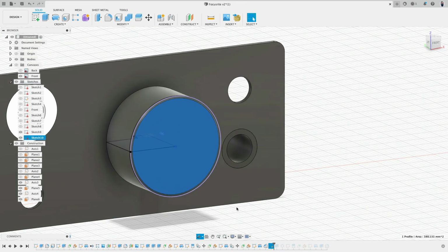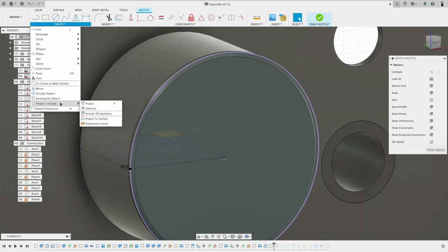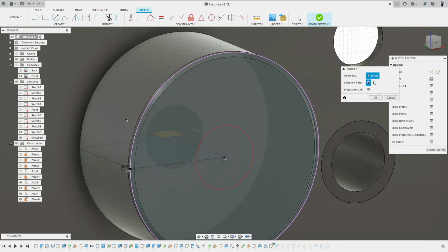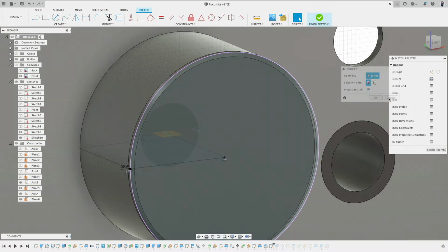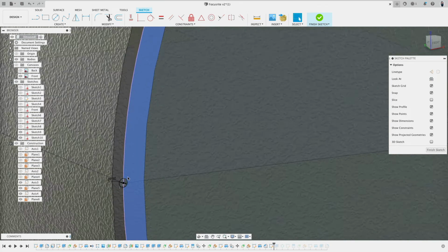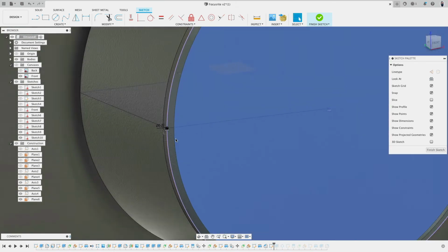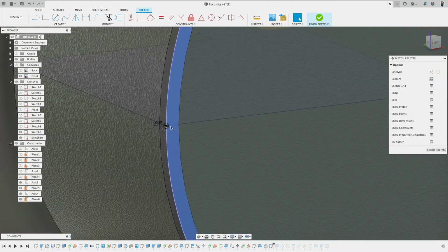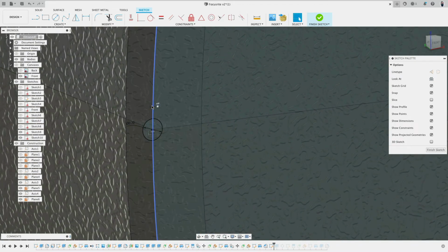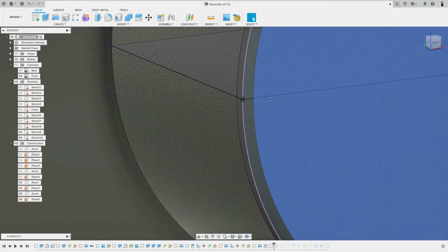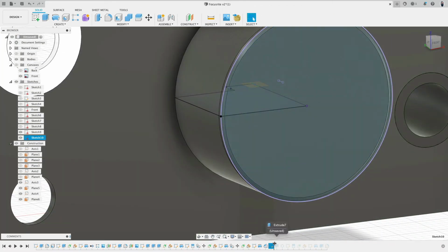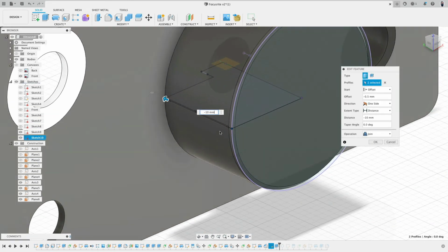Then on this face, we will create a sketch, and I will via project this edge or this face into, actually here, this edge I will project in. That's then the way how I got this. And then I will create there a small, really tiny ring, 0.25 millimeters. There you see, and make this one horizontal constraint to there. And the ring is glued onto this line too. Okay, so why did I do this? Well, the next step, pure magic. We will extrude now that profile.